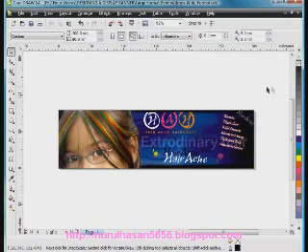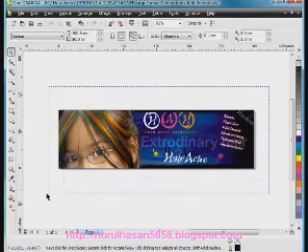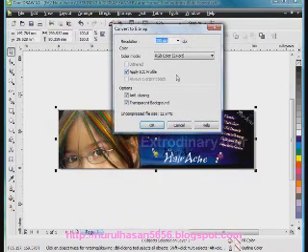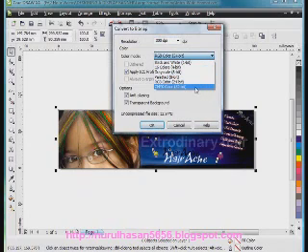For me, I would convert the entire thing to a bitmap, just to help me play it safe. You see, if I select my entire image, go up to Bitmaps and Convert to Bitmap, and in fact, right now we'll actually discuss, should we convert to a CMYK or an RGB color bitmap? There are a lot of issues around this, but for right now, most modern sign printing plotters print using more colors than the standard 4 CMYK colors.